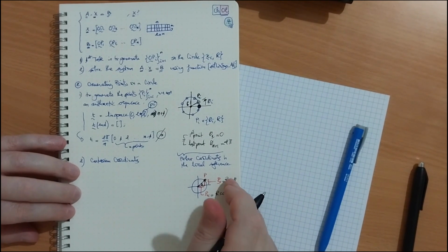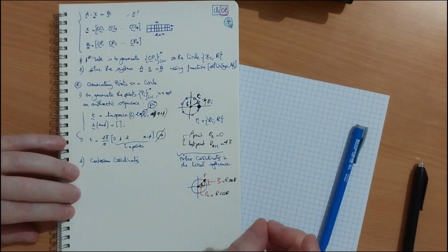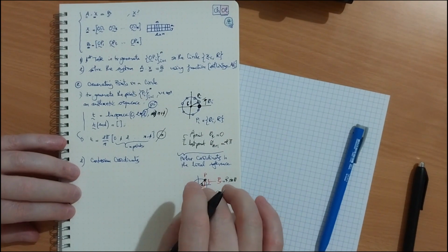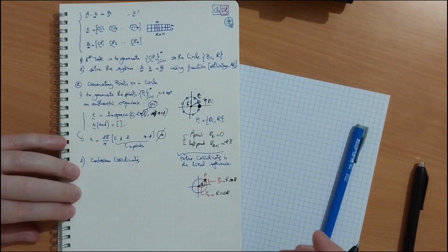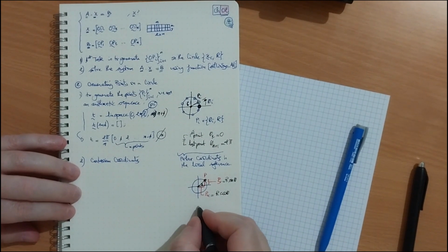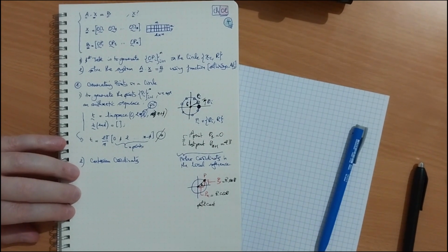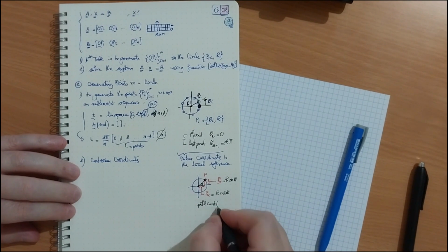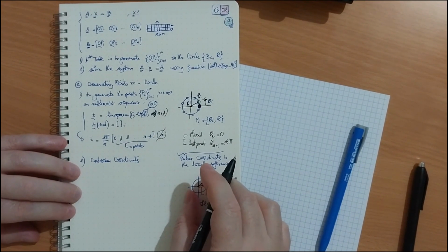We could use the functions sine and cosine, but it's better in MATLAB to use a built-in function dedicated to this problem, to transform the polar coordinates to the Cartesian coordinates, called pol2cart. To pol2cart, you should give the angle theta and the radius, the length of the hypotenuse.